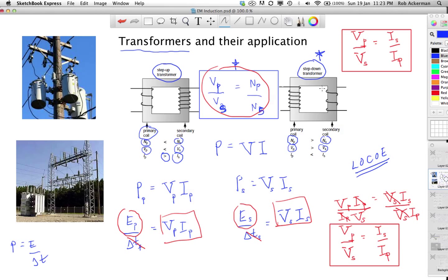Well, there will be a transformer built into your phone which will drop the voltage. But why would we ever need to step up the voltage? Maybe you can think of an example in your home where you need a higher voltage. A good example is a television, which may operate at a higher voltage, especially the older televisions that use what's called a cathode ray tube. There, 120 volts is not enough, and we got to increase it.